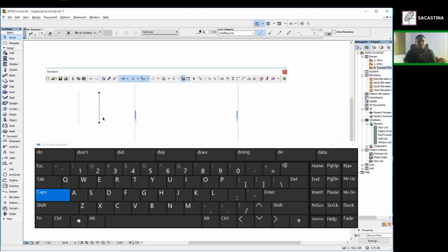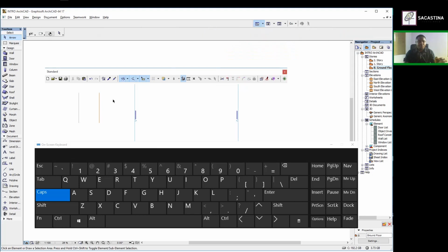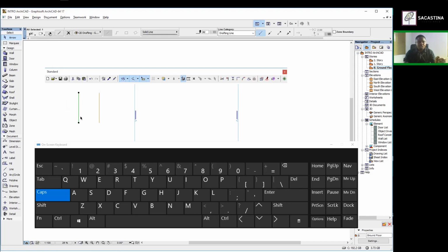Now you want to pick. Let's say this line is kind of yellow in color. Now you want to pick this parameter and impose it on this one. What you do is select these two. You go closer to it, it changes to blue. You click it once and it disappears. You go back, select Inject Parameters, select it, and click it on this one. You see it has gone back to look like this other one. That's what it does.